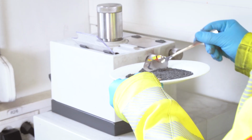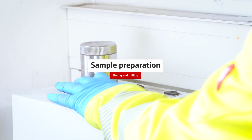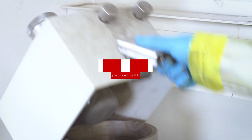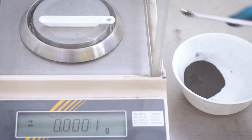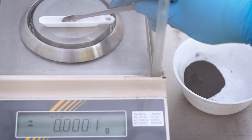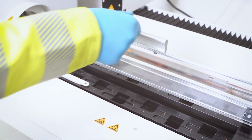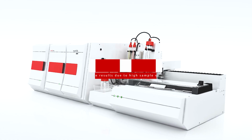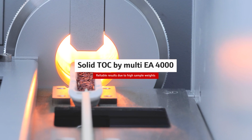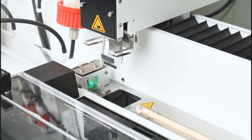The next sample preparation steps in the lab are drying and milling to reduce the particle size in accordance with international standards. For direct TOC determination by the multi-EA 4000, the sample is weighed into a ceramic boat and placed into the autosampler. The automated analysis of TC and TIC in solids is carried out using the multi-EA 4000 with the TIC